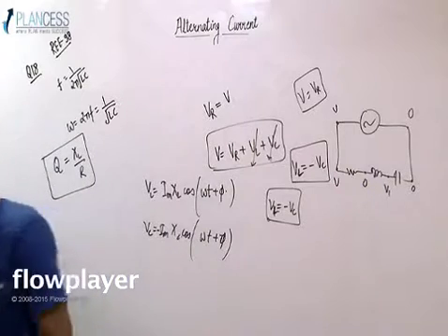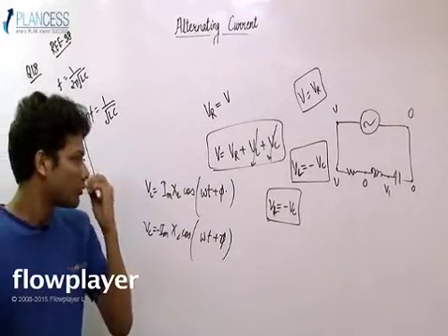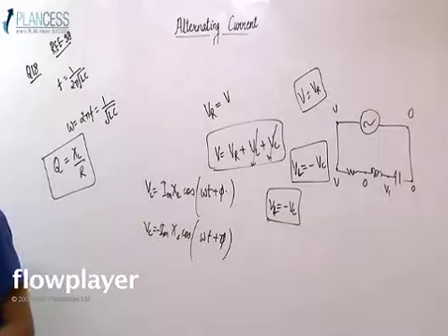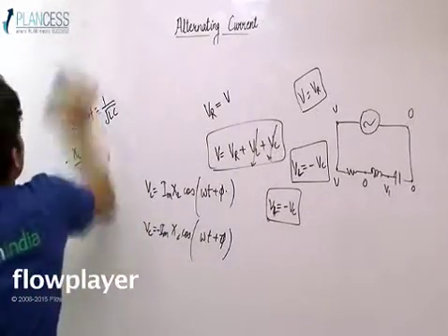So the question is, the quality factor of the circuit is omega L by R, or 1 by omega CR, and this is the measure of the voltage magnification. Yeah, this statement is also correct. So we got 3 correct statements. So this was our question number 18.